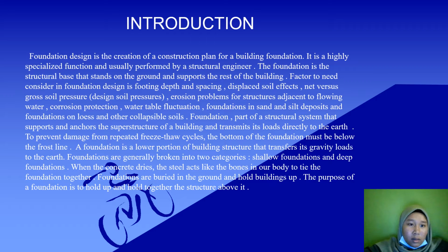Factors that need to be considered in foundation design are footing depth and spacing, displaced soil effect, net versus gross soil pressure, design soil pressure, erosion problems for structure adhesion to flowing water, corrosion protection, water table fluctuation, foundations in sand and silt deposits, and foundations on loose and other collapsible soil.